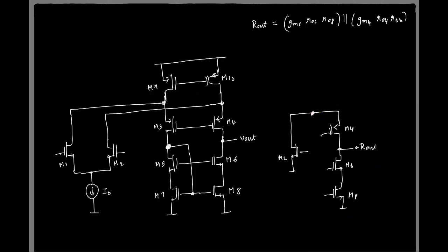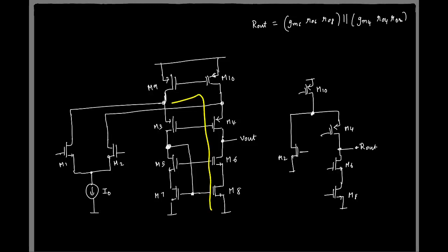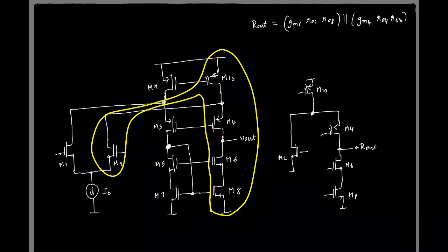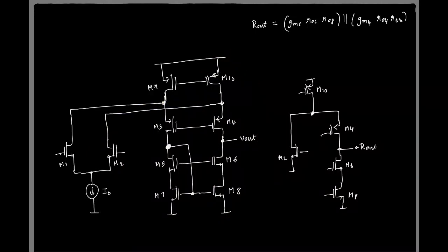So now you will have the additional transistors M9 and M10 loading here, right? In the single-ended picture also, right? Because now you have this entire portion as the single-ended. Okay, is that fine? So now can you tell me what will be the new output impedance?